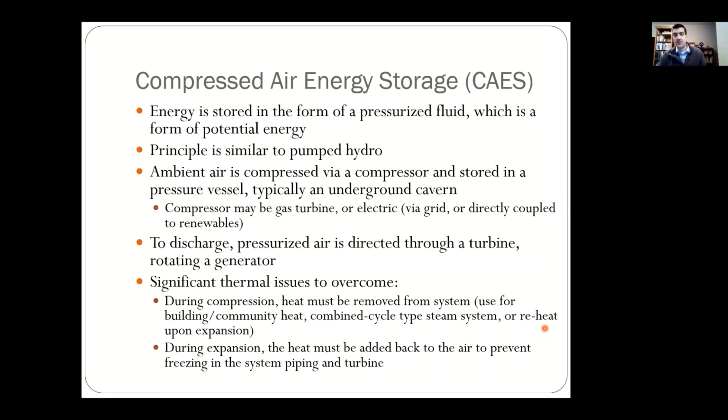It's more intuitive that when you compress the gas, the temperature rises. What may not be quite as intuitive, but it's definitely true, is that if you take a gas and expand it, the temperature decreases. And that can be a real problem if there's any moisture inside that gas. It's air, inside a natural cavern, so there's going to be natural moisture inside that air. As you expand it, the moisture is going to freeze, and that's going to clog up the pipes, and then the whole system comes to a stop.